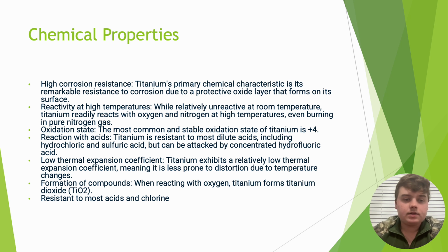Reaction with acids. Titanium is resistant to most dilute acids, including hydrochloric and sulfuric acids, but can be attacked by concentrated hydrofluoric acid. Low thermal expansion coefficient. Titanium exhibits a relatively low thermal expansion coefficient, meaning it is less prone to distortion due to temperature changes. Formation of compounds. When reacting with oxygen, titanium forms titanium dioxide. And titanium is resistant to most acids and chlorine.